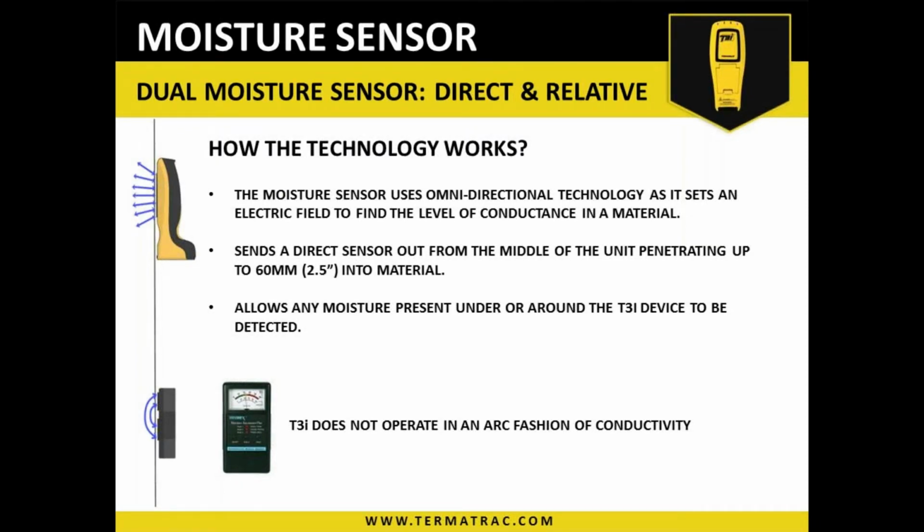Now, the meters do come into the same group of test equipment, which is known as a non-invasive dielectric moisture meter. Non-invasive, it just sits on the surface of the material. Dielectric is telling us that there is an electrical current that's emitted from the device, and it's from that electrical current through impedance, resistance, and such that makes the needles move.